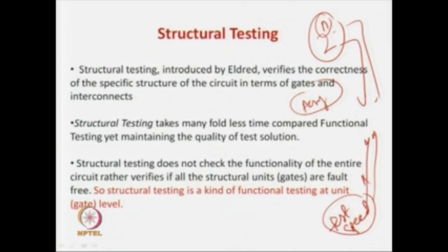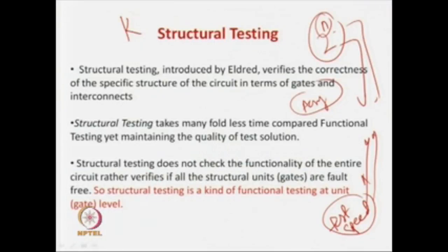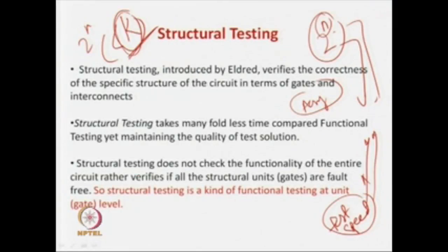But statistical results, or history, have a very important role in testing. In testing, you apply a certain kind of test strategy and then you see the outcome for around, say, 2 to 3 years in different manufacturing industries. For example, let us assume that somebody has found a technique in which you can apply only K patterns to test a circuit, where K is very, very much less than 2 to the power n. Then we keep using this number of test patterns and keep testing the circuit and doing the binning, that this is a normal circuit, this is a defective circuit, but we do not apply 2 to the power n, we apply only K test patterns. Now you have to find out the accuracy, that is, what wrong you have done.